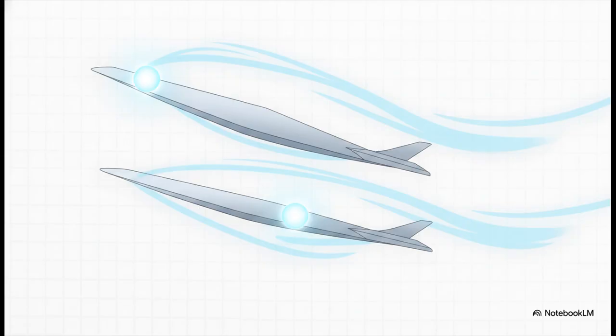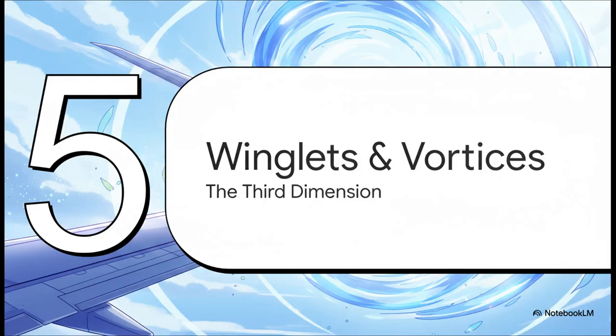All right, pay close attention here because this is an actual safety briefing. The average of all these pressure variations we've been discussing is called the center of pressure, or CP. And as your instructor, I must emphasize this absolutely critical safety point for your flight maneuvers. As you change your wing's angle against the wind, that center of pressure physically moves. It actively shifts forward at high angles of attack, and it moves aft or backward at low angles of attack. This directly impacts the aircraft's aerodynamic balance, the structural loads on the wing, and most importantly, your ability to maintain control in the cockpit.